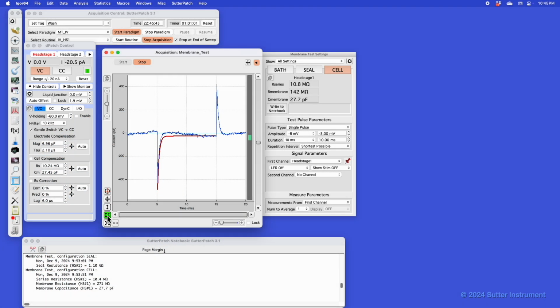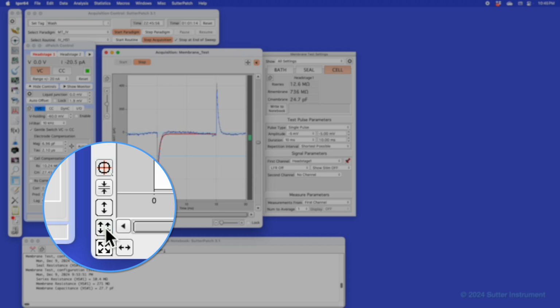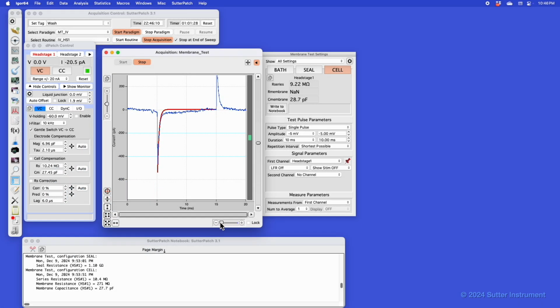Continuous auto scale will keep changing, as you just saw the axis jump from sweep to sweep. It continuously auto scales a sweep. In membrane tests, you really don't want that because it's just jumpy, and the signal doesn't change so much. So we could disable that, and of course we have the buttons to work on the individual signals. You could auto scale the signal one time. In the y-axis, you could center it, and you could also reset the x-axis if you were playing around with any of the controls here.